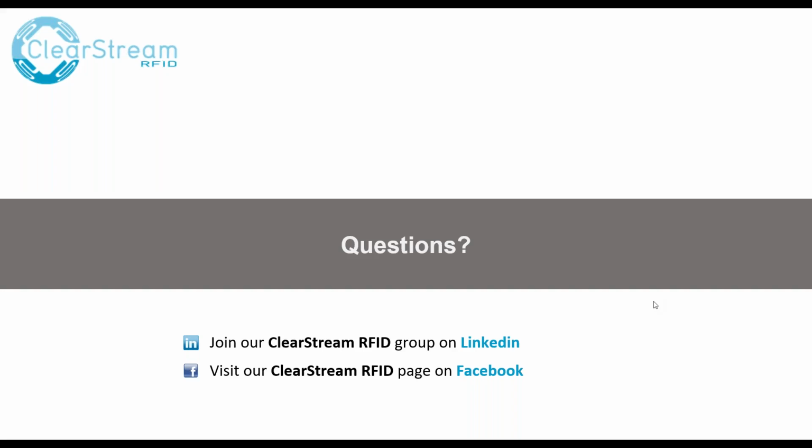There's a question here I'd like to answer: does the R700 have to be set to LLRP or IoT mode for ClearStream to work? You'll want to set it to LLRP mode. So if you download the trial and install it, just make sure it is in LLRP mode, not IoT mode, to have it work.